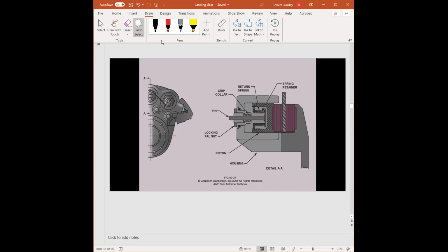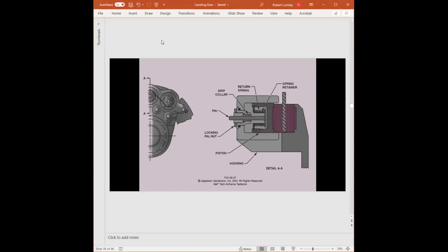So really, we just need the piston to move 1/4 of an inch for the pads to grab hold of the disc. Well, what then happens? Let's say, and I'm exaggerating here, that 1/4 inch of pad is now worn off. If the piston always returned back to its initial spot, way back here, then the next time the pilot applies the brake, not only do they have to move it 1/4 inch, but also the extra 1/4 inch that the pads have worn. So now the piston has to move 1/2 inch before the pads make contact with the disc.